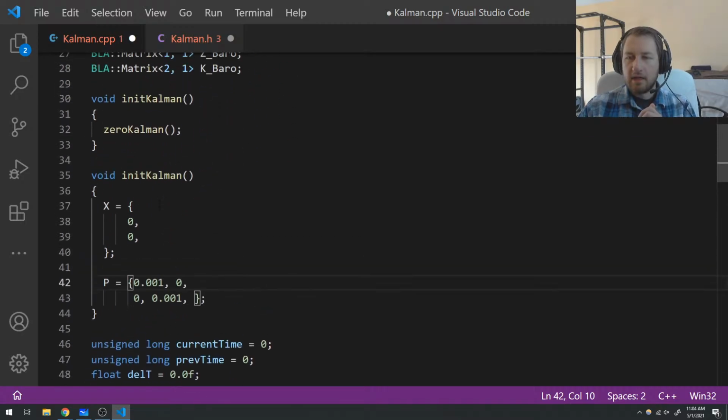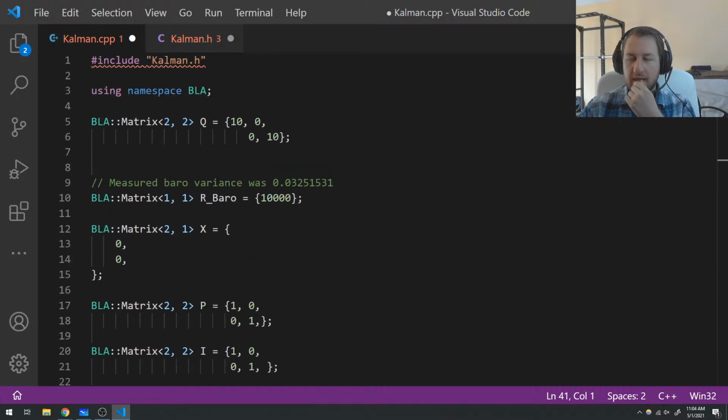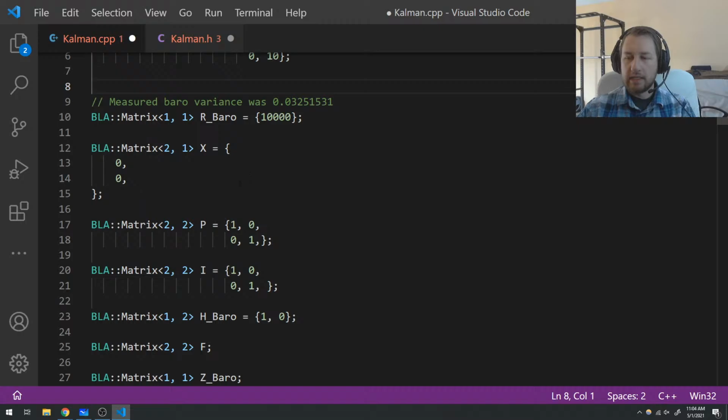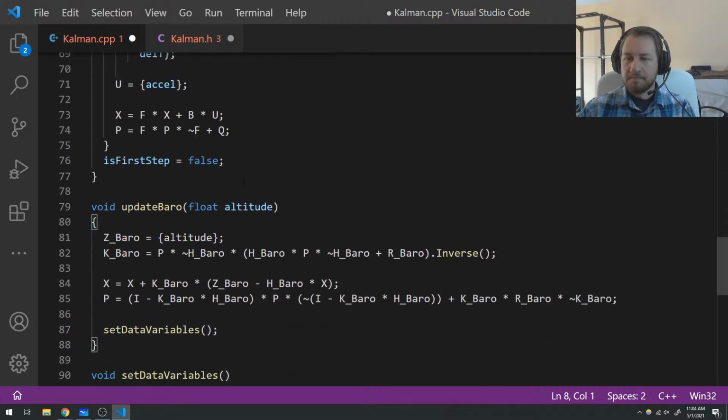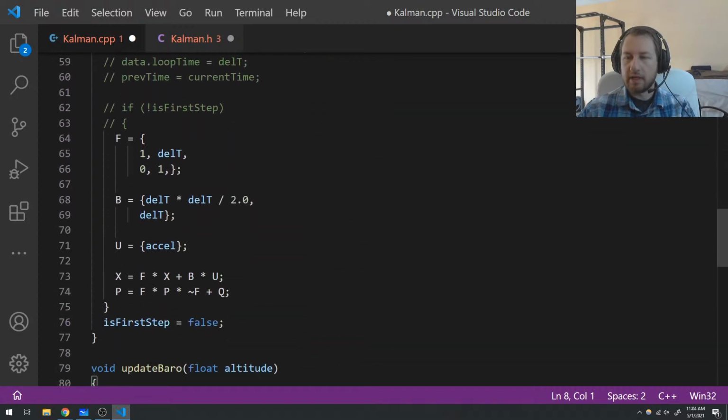It's kind of harder to explain how to set these correctly. And it really depends on a case-by-case basis. Even I'm not very sure exactly about how to set these. But you play around with these values. I've done a bunch of playing around with the values and testing and seeing what the graphs show me, and seeing if they make sense, right? But yeah, that's another form of this Kalman filter that you can use, where the acceleration is the input.